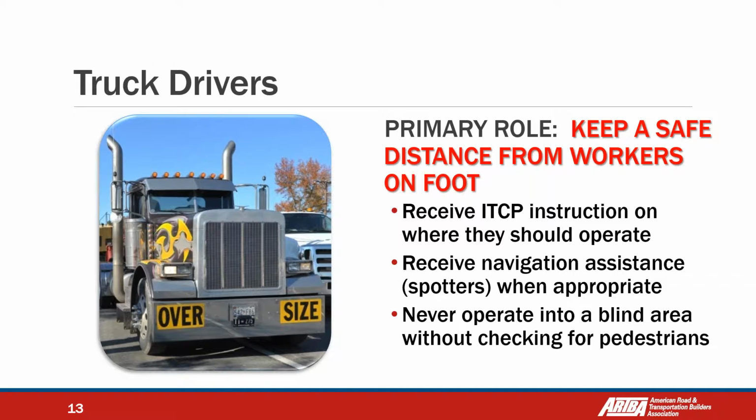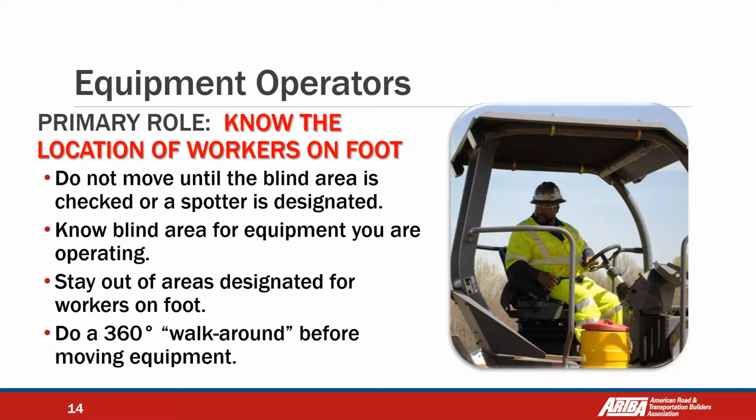Okay, some rules. Backing up operations with dump trucks are critical activities, because most of the accidents we have inside the work zone are because of dump truck backing up operations. So equipment operators in general, or regular workers, operators working in the work zone, must know the location of workers on foot. It's very similar to the regular dump truck operators.